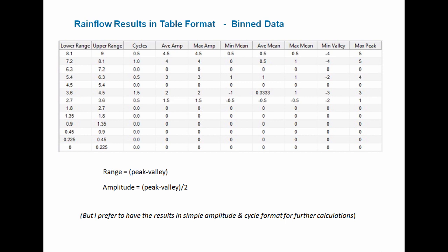Well, it has been traditional, and Steinberg does this, for example, and as have many other authors, to take our data and group it into different sigma levels, for example, and then to feed the data into a Miner's cumulative fatigue type calculation. But my approach is different. I say, okay, I'll make this table just to humor the people who need to be humored in that regard.